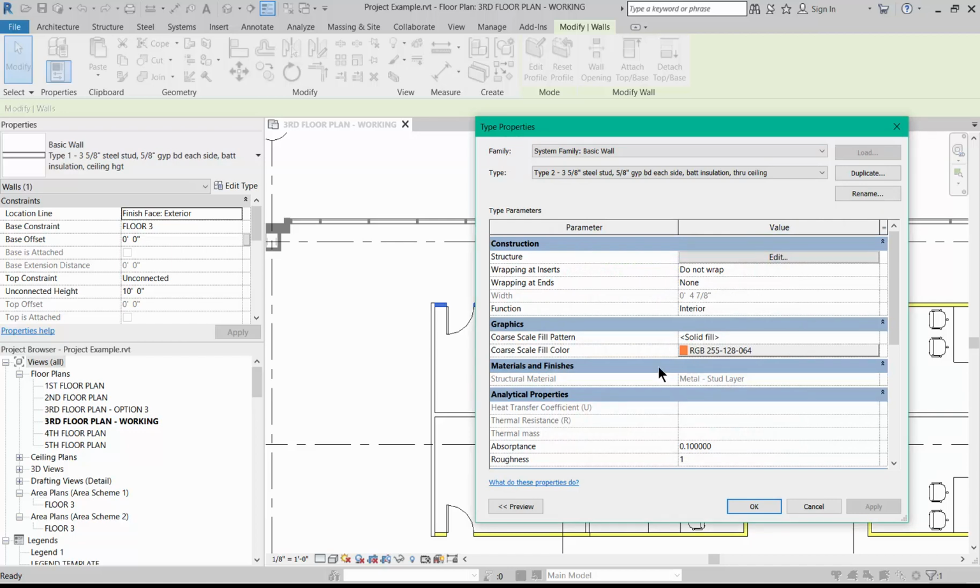And usually when I pick colors, I go from lighter to darker, or I keep the coloring, so every wall, as it gets more complicated or it has a special assignment to it, the colors are related. So in this case, I will start with the yellow and progress towards reds and purples with the more sound protection that each wall has. And you will provide additional description of each type in your document, but this is sufficient to define it as you're selecting them on the plan. Okay, so this is all I need to do.